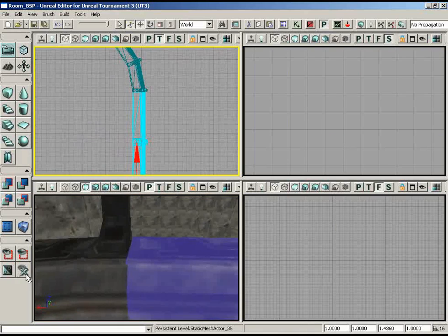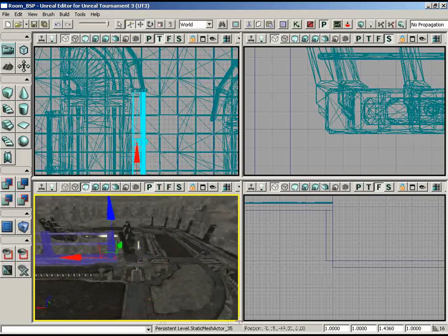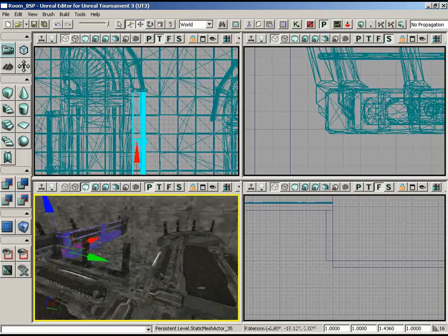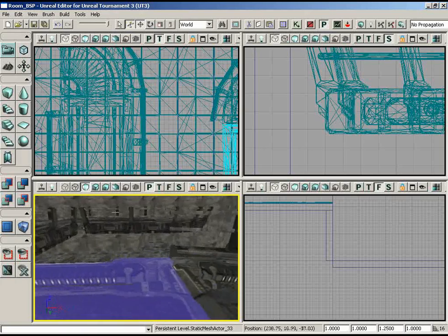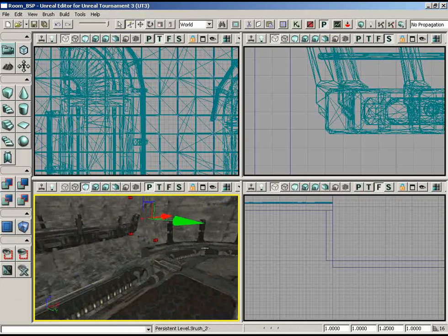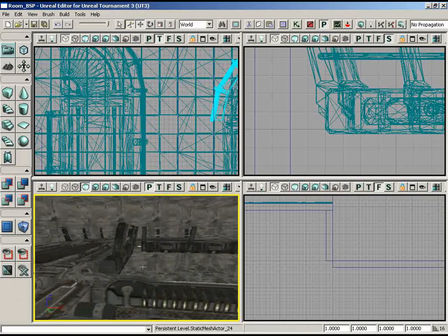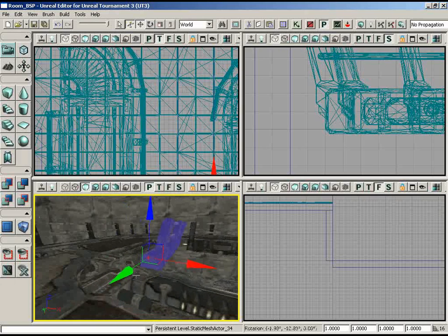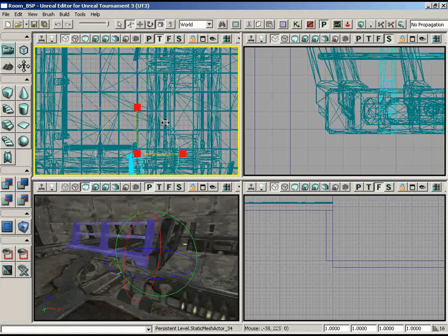So let's once again bring all of our meshes back, and let's see. That's now looking good for that guardrail. What places do we have left? It looks like we've got 2 left for this piece. So looking at this side, we're going to need a guardrail for this side, seeing how we have a non-supported edge on this side, and we know we need a support for the corner. Let me grab this piece that has a support on both sides and duplicate that over. So once again, I'll do a rotation of 90 degrees in a duplication and move that into place.